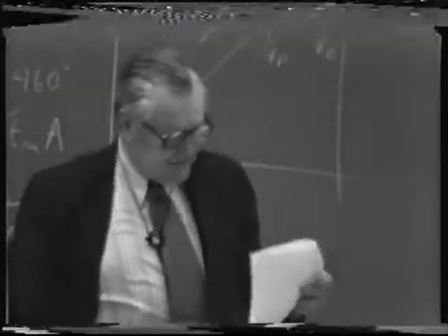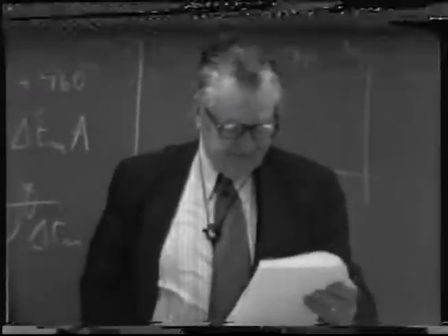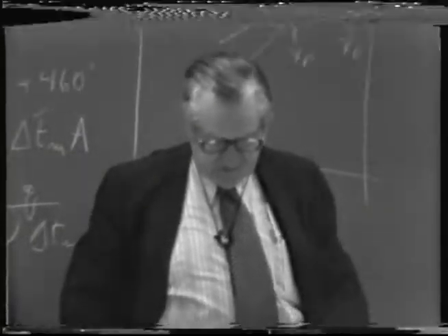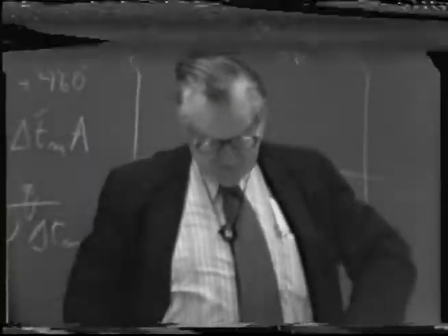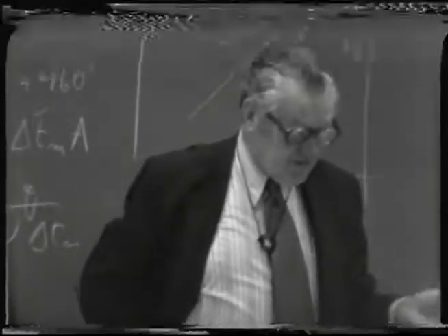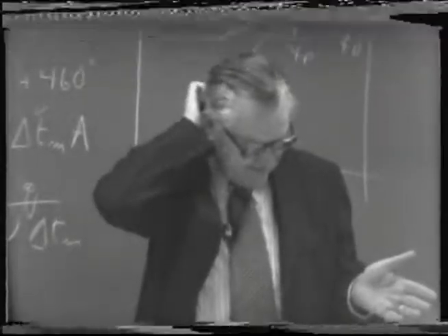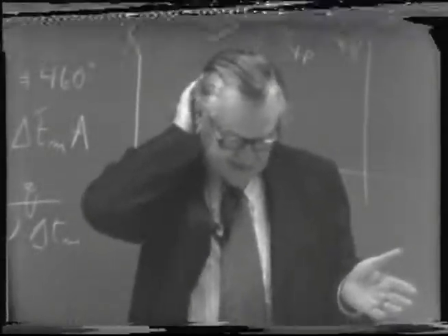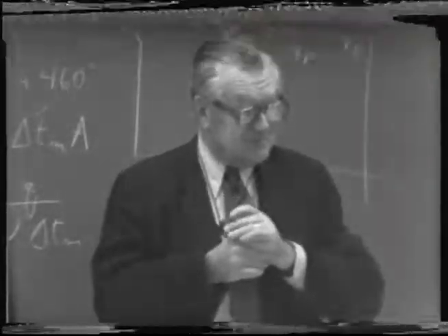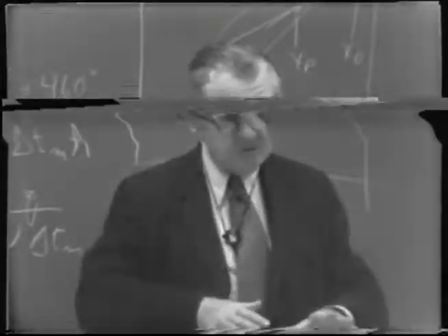That's a pretty big heat exchanger, and it's very possible that my statement of the overall heat transfer coefficient of 125 BTUs per hour per square foot per degree Fahrenheit is not realistic. It sometimes is realistic, though, because you get fouling in the tubes and coating of the tubes, and then the heat transfer coefficient drops off significantly.